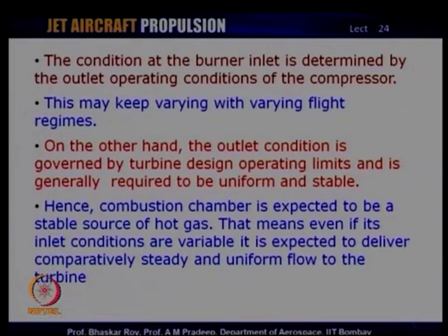Depending on whether the aircraft is taking off or it is climbing, or whether it is cruising or it is doing maneuvers, the compressor operating condition and its delivery to the combustion chamber would vary in terms of pressure, in terms of temperature, in terms of density, and also quite often in terms of the velocity with which they are delivered. Now, this variation obviously has some impact on the combustion chamber performance.